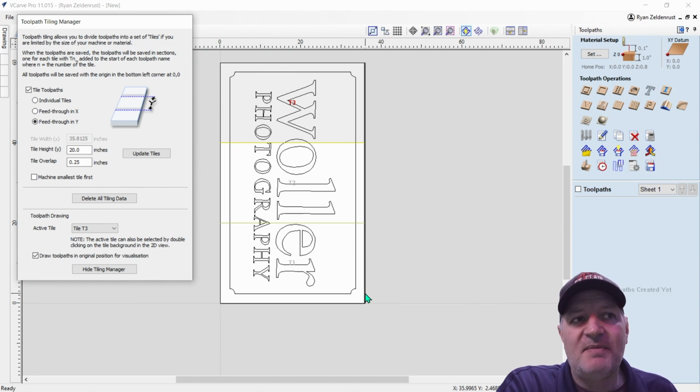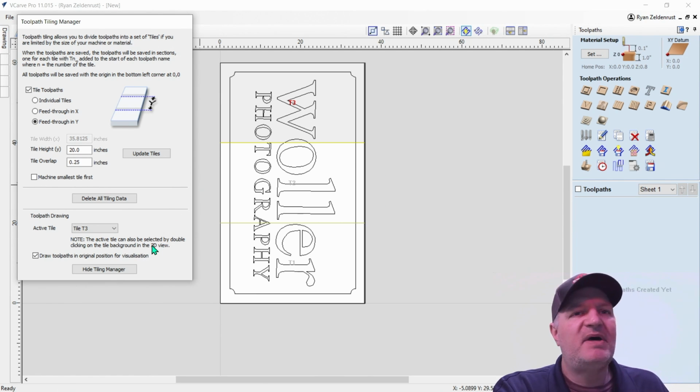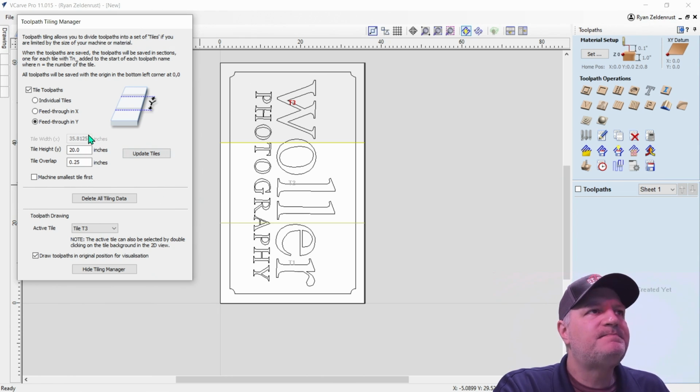Now on this project, I'm going to drill holes directly into my project because it's going to be painted, and then I'll just leave the dowels in, and they can paint right over them. A lot of times you'd get your project wider and put holes on the outside and cut them off later, but I'm not bothering with that right now.